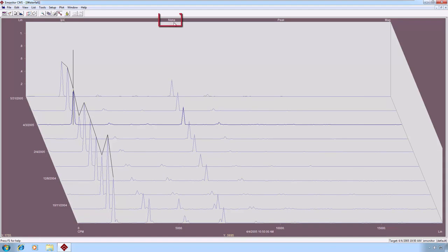We're currently using no filter on this particular measurement, and you can also toggle peak signal detection to peak or RMS. And down here, you can track your speed in either CPM, in orders, or in hertz. Then the x-axis scale will change to reflect that. All right, let's move on.